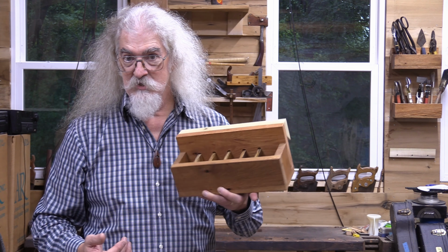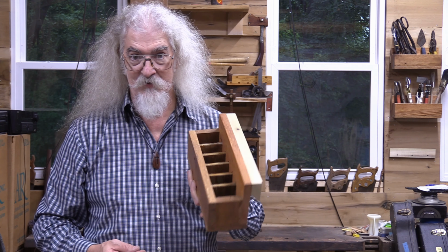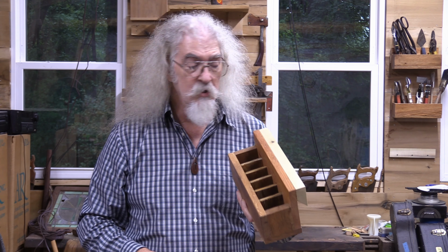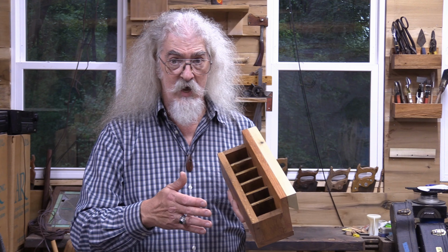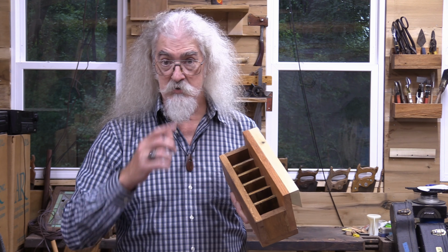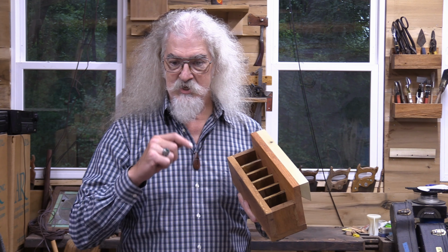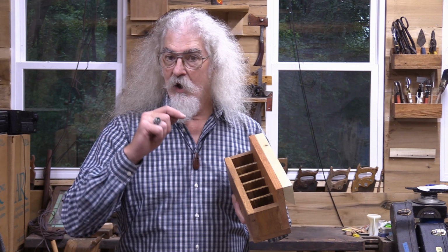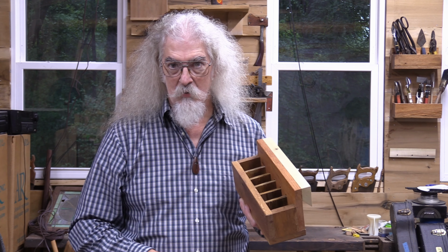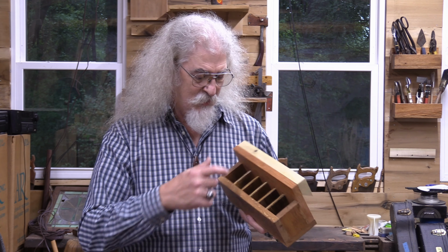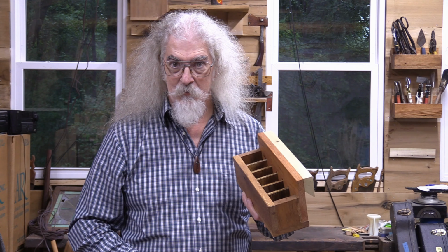Well, I have a CNC machine, and that's actually a perfect thing for the CNC. So I wrote a little bit of G-code by hand for the CNC. I didn't do this in a CAD program. I just wrote the instructions to tell the CNC where to go and when to cut and when to move and when to stop. And I stopped it at the point at which I could simply restart it. So here, let's look at the G-code for the CNC machine and see how I wrote a little program to cut these repeated slots.